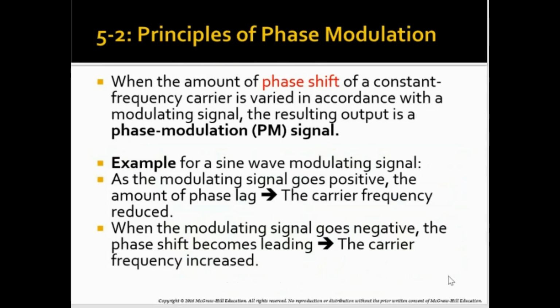Okay, this is phase modulation. Similar to what we talked about with frequency modulation, phase modulation is also very similar to frequency modulation, but here, when the amplitude of your modulating signal changes, we change the phase of the carrier. Instead of changing the frequency of the carrier, the phase of the carrier changes.